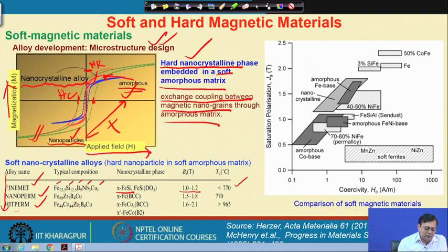But with the development, if we remove the silicon and, let us say, the niobium and simply add zirconium into it, then we get again that alpha iron, that is the basic design consideration of the microstructure, but we can achieve a higher value of the saturation magnetization of 1.5 Tesla to 1.8 Tesla, and the temperature is also increased. The temperature means the Curie temperature, means the material could be used at a higher temperature.